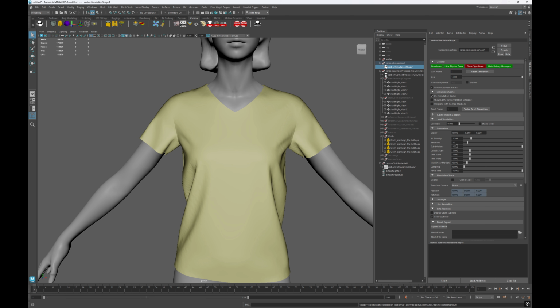Now these are probably higher settings than you normally would use, but if you want to get a good weft warp bias behavior, then you need convergence of the simulation, and to do that you need a reasonable amount of simulation. And if you've got a fairly fast machine with 24, 32, 64 cores, then this will still run pretty quick. While we're here, we also need to set the length scale, because our character's in centimeters, into centimeters. It defaults to meters, but we're going to set it to centimeters, and that's the simulation settings done.